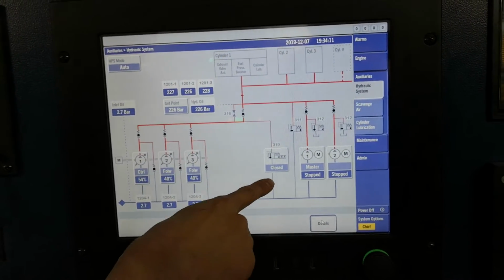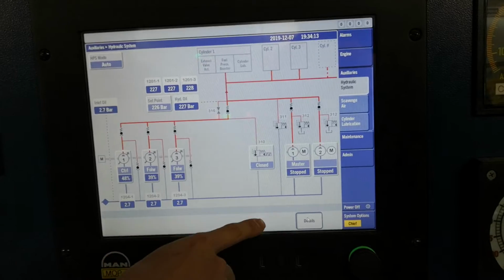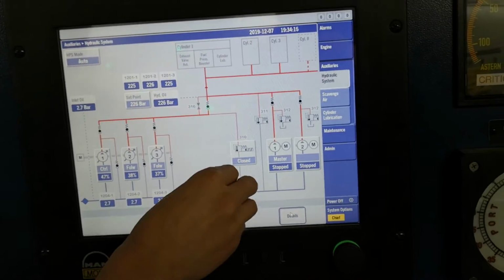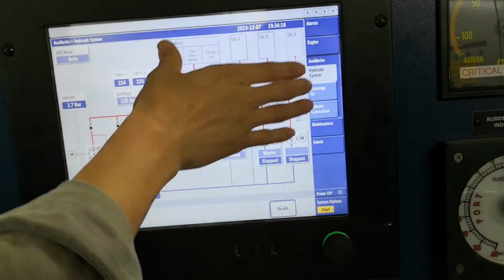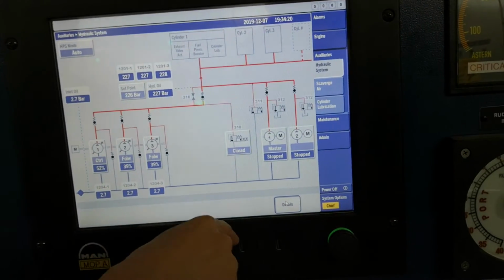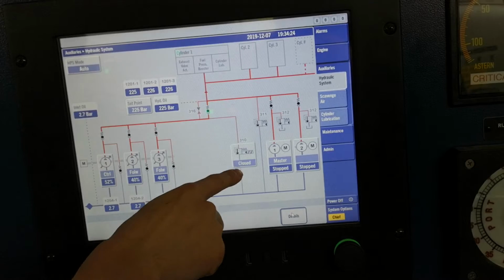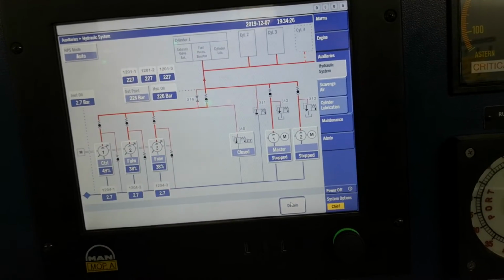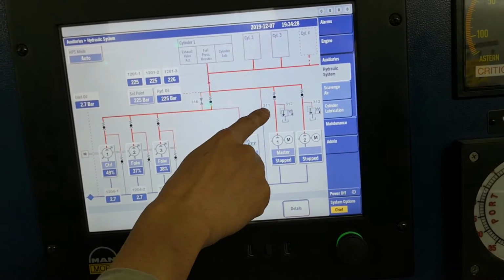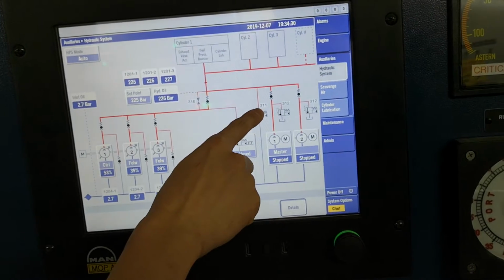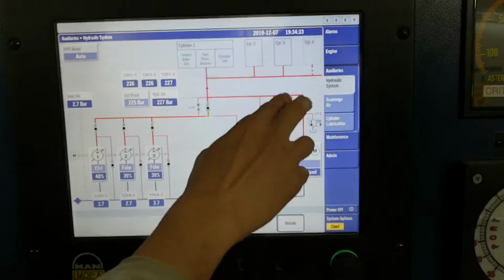You know the 310. When the engine is shut down, this valve is open and releases all hydraulic pressure to here. So in case of some leakage, if the pressure cannot increase, you may doubt this valve for leakage. Also 311 is adjustable, also a relief valve for this startup line.